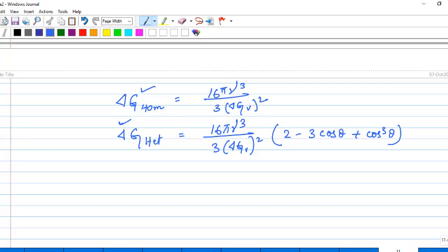So that is how you get a higher nucleation rate also in case of the heterogeneous nucleation. And higher the nucleation rate, lower will be the grain size, and that is how the heterogeneous nucleation leads to a finer grain size in the solidified material. Okay.